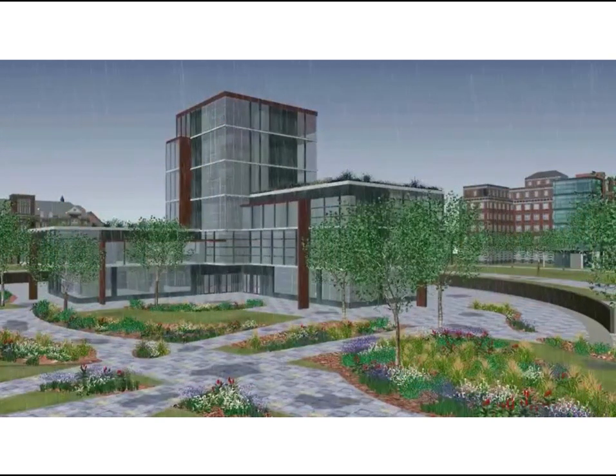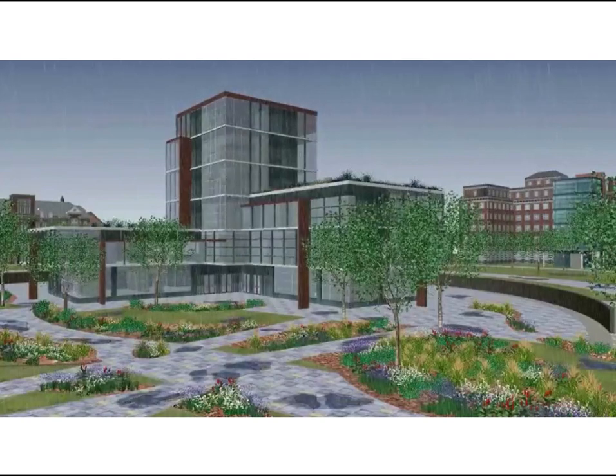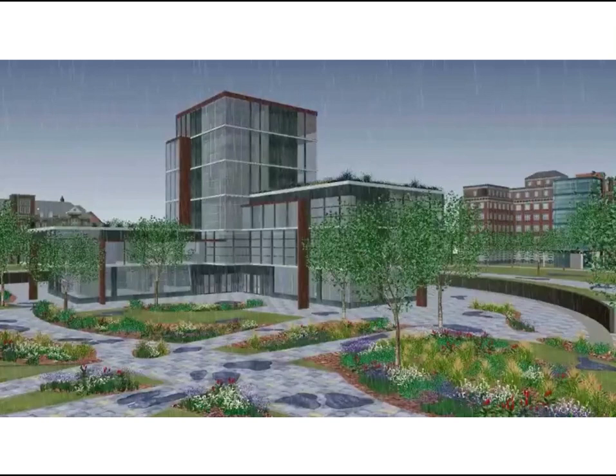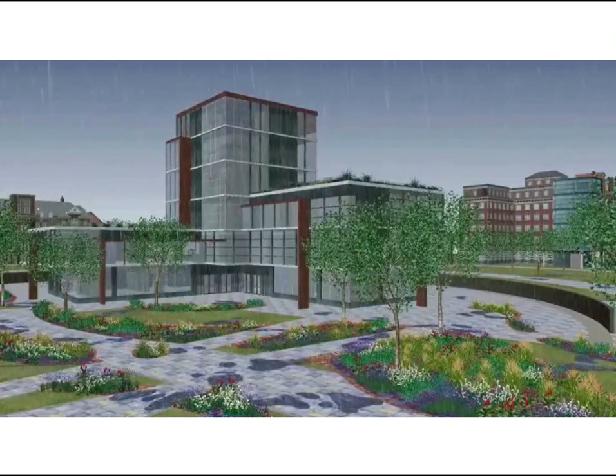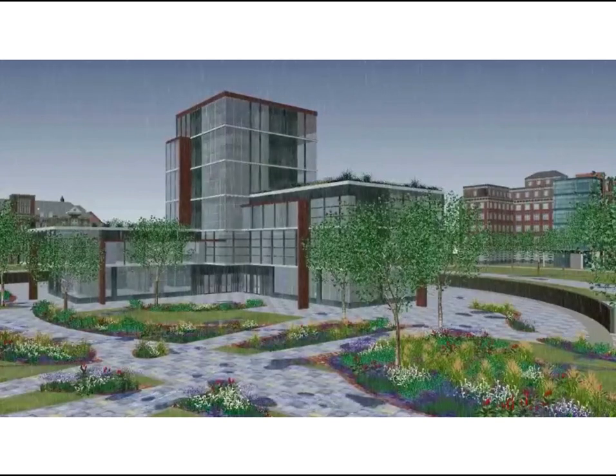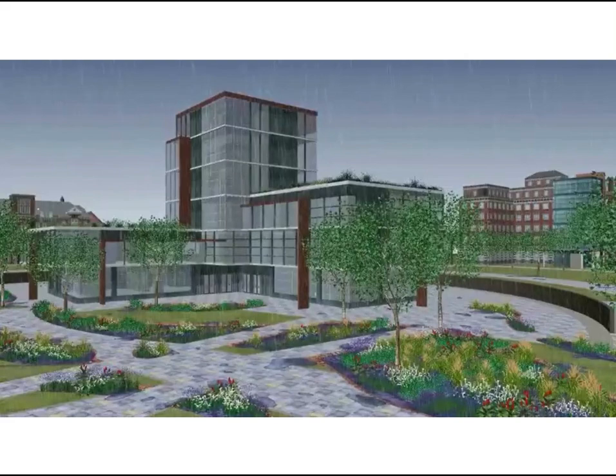Now when it rains, water does not collect into large pools. Instead, our three systems absorb and redirect the excess runoff. The green roof prevents a lot of water from entering the storm system or hitting the ground. The porous concrete pavers absorb some of the rainwater and direct it downward into the aquifer. And the rain garden accumulates the remainder of the rainwater, preventing flooding and damage.